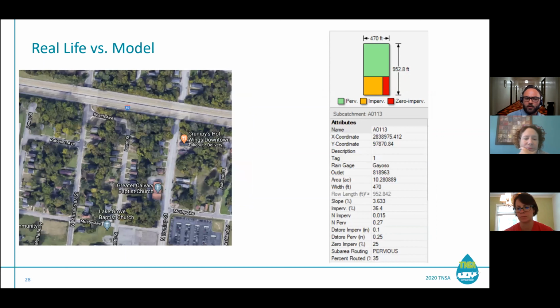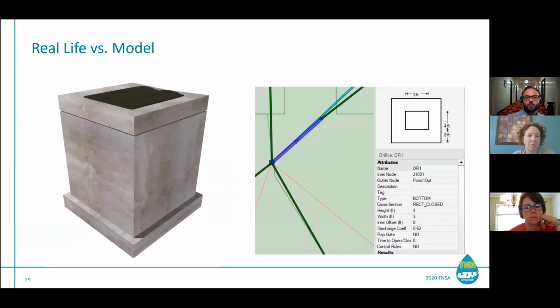And then you look at a neighborhood and you can distill that neighborhood down into pervious and impervious area, and then the impervious area into which impervious area runs directly into inlets and which of it runs across yards and other pervious area. And it gets pretty weedy when you look at that, because each of those has different factors that help know how much runs off, how quickly it runs off, and where it runs off to.